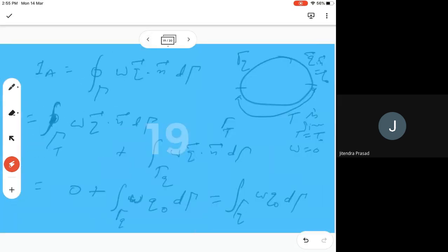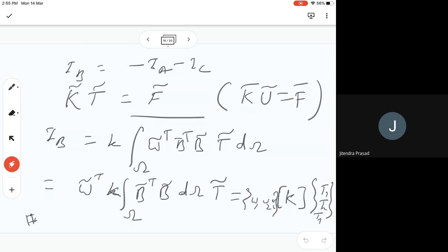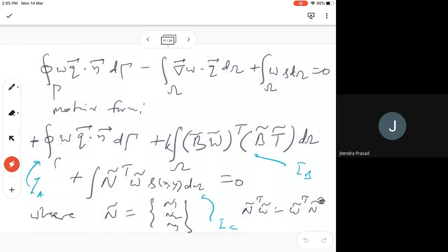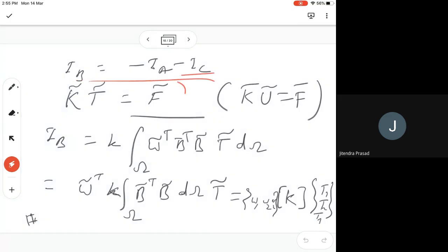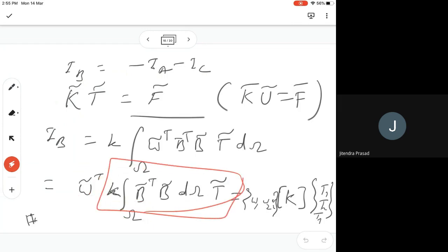Meaning that whatever you see here, all these equations you can change into this form, and finally this will be in this form, because there will be W terms here, W1, W2, and as you know W1, W2, W3 are arbitrary, finally you get these values, right? So basically this is nothing but this multiplied by this, and this is the stiffness matrix.